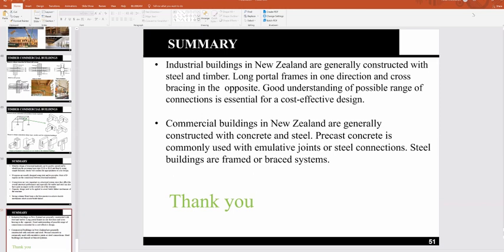If you give the connection, timber to steel, you have already shown some pictures. How can you take the transformation? What you need to make sure, first, is that there is no failure in your timber, by providing enough edge distance. For example, with a steel connection, the edge distance is 1.5 times the bolt diameter, whereas for timber, all of a sudden it goes to 8 times the bolt diameter.